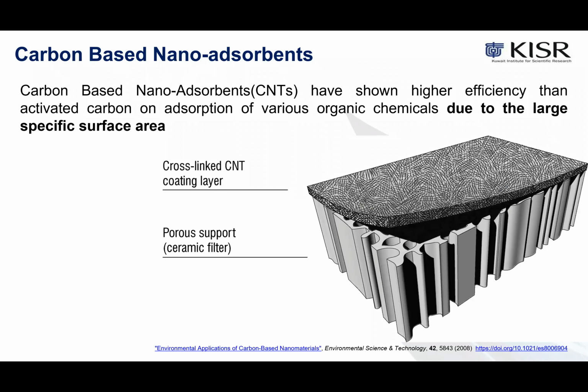The second, we have the carbon-based nanoadsorbent, which is a widely used method for home water filter treatment because of its ability to improve water by removing the disagreeable taste and odor, and it can be effective against microorganisms. However, it does not affect total dissolved solids. So there will be some toxic particles that exist, even when we are using this kind of filter. But the carbon-based nanoadsorbent has shown very high efficiency recently due to the large surface area.